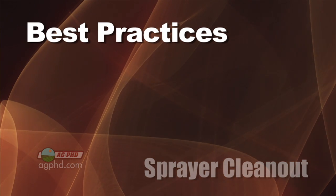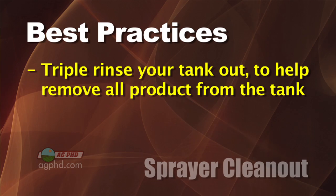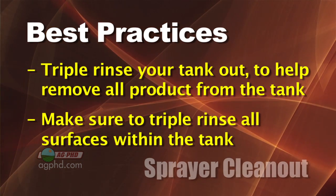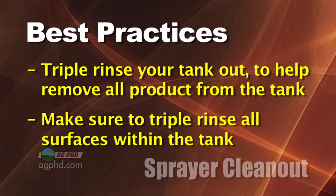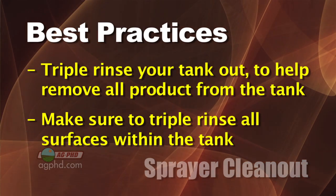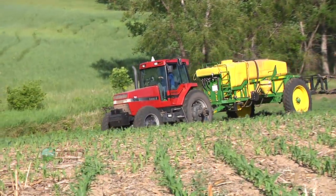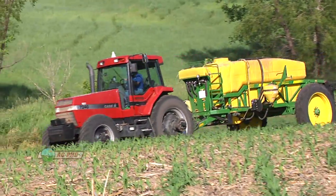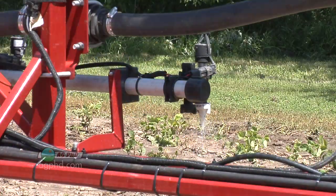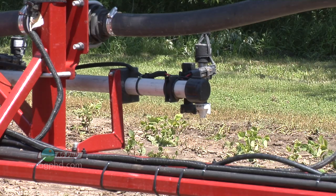Then in terms of how you're going to clean that tank out, we talk very often about triple rinsing. I think that's a great thing, but just make sure when you're actually triple rinsing, you're triple rinsing everything. In other words, when you've got that big poly tank, how about the top of that tank? I mean, not the outside, but the inside top of that tank. A lot of times ag chemicals will splash up there, or there'll be foam, and that foam will stick on the top of the tank. Yep, something will happen, but you've got to clean out there. You've got to clean out the boom, maybe even the spray nozzles. I mean, you've got to really, really be thorough.